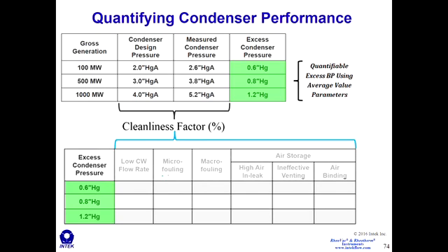Now, fouling, everyone should be familiar with. That's how dirty or obstructed their tubes are, and that can increase condenser pressure. Also, if there's lower flow rate through the condenser than what is being used for a cleanliness calculation, then you can have an indicated low cleanliness factor.